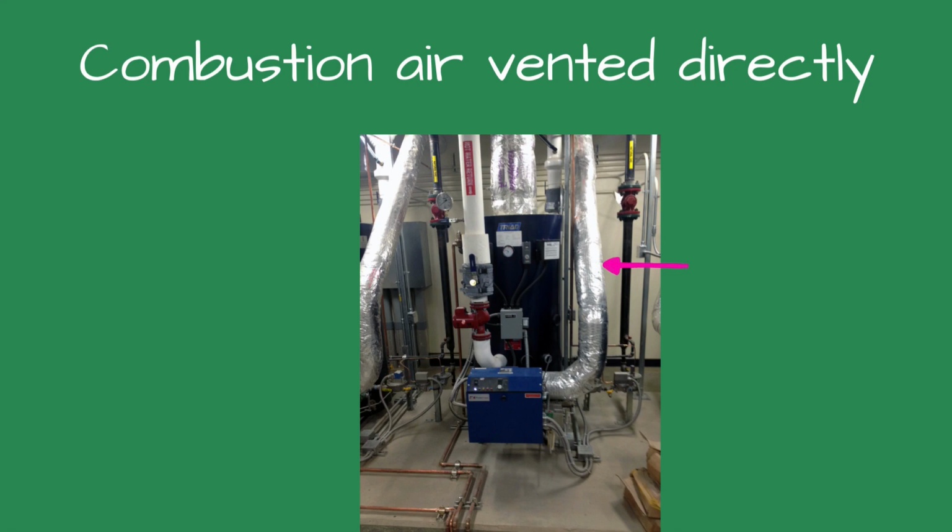One of my cautions when using ducted combustion air is the duct sweats when bringing cold air into a warm boiler room. You may have to insulate the duct to avoid the water dripping onto something important. Another consideration is the duct inlet on the outside of the building. You will need a screen so the critters cannot get in. It will probably need a rain shield, so rain will not enter the duct.